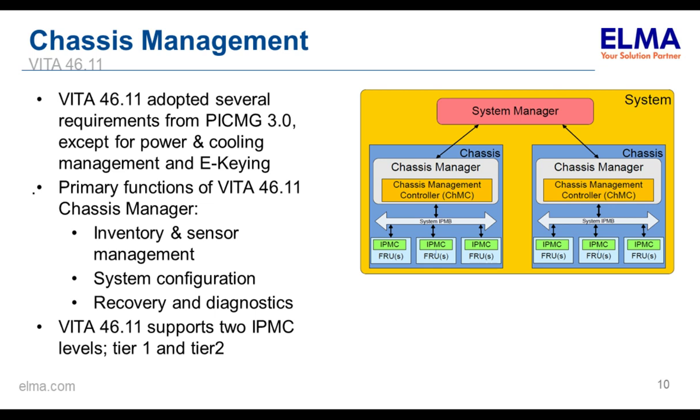So then moving on to the VITA 46 chassis manager. VITA 46.11 adopted several of the requirements from the ATCA shelf manager, except it did not include the power or cooling management or the E-keying requirements from ATCA.